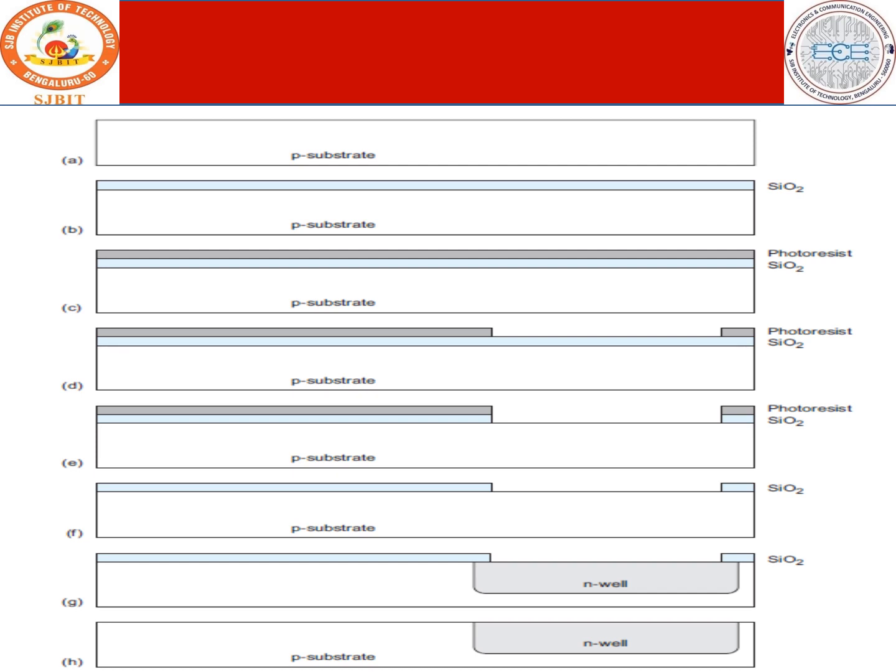So already you must have got a view that this is the place where a well structure is being created. And next, scrape the oxide also. You notice the oxide is also removed. Now what do you observe? Photoresist is also removed, only oxide is there, and you have almost a well structure ready, and do the necessary process of either diffusion or ion implantation in order to make it N type. Finally, you notice this is your well structure. Okay, this is how the well structure is created.